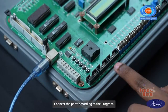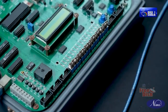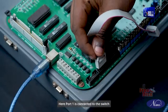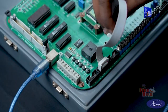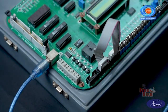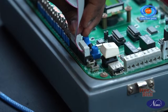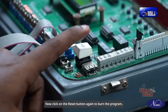Connect the ports according to the program. Locate the ports, switch and LED in the kit. Use FRC cables, female to female, for connecting the ports. Here, port 1 is connected to the switch and port 2 is connected to the LED. Now click on the Reset button again to burn the program.